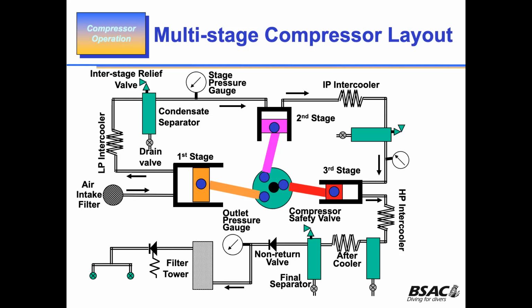But when it gets into the cylinder, it will pressurize the cylinder until the cylinder is the same pressure as the discharge from the third stage. And that's what you're aiming to do. And that's why it takes some while for you to use a compressor to charge a cylinder.